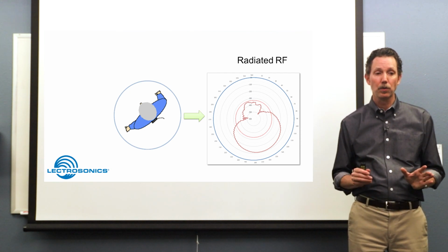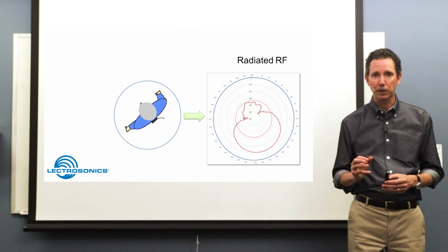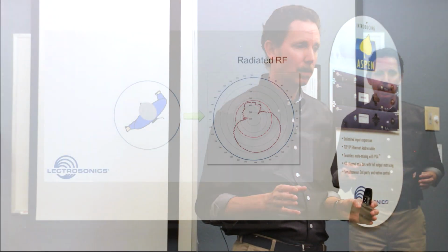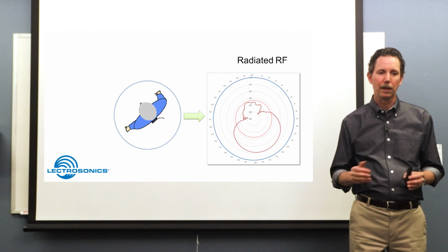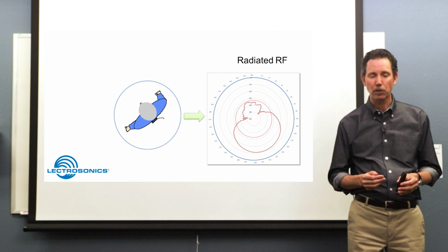Here's an illustration showing that although it's often a good place to put the bodypack transmitter in the small of the back so it stays out of the way and isn't blocked by the arms, you're generating what is sort of like a cardioid pattern. It's a directional pattern based on the position of the body in relation to that transmitter. So keep in mind that if you do this kind of mounting, it's best to have the antennas somewhere behind the person to get the best signal.